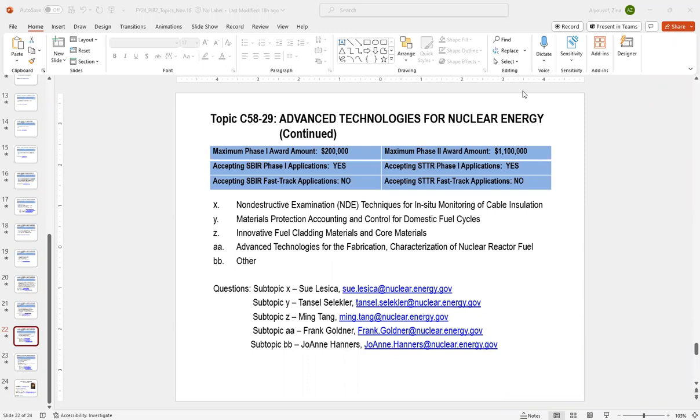Because the fuel cladding material is in contact with nuclear fuel, and the outside faces the coolant, we need to consider FCCI or FCMI, and also higher temperature, radiation dose, and corrosive chemical environments.